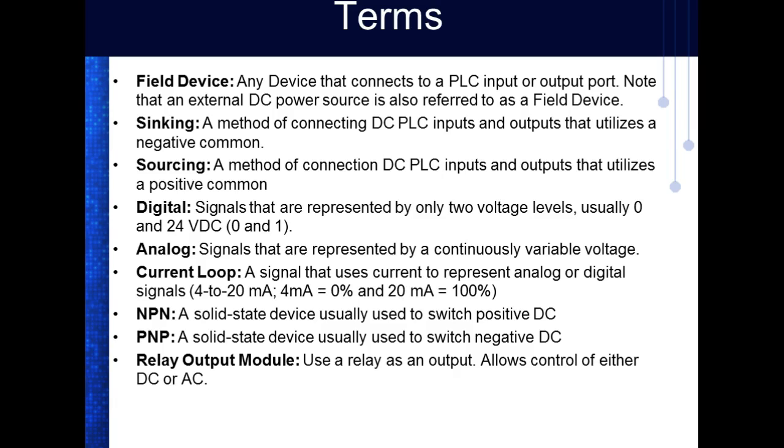And the problem we have is that when we put current through a conductor, it generates a magnetic field. Well, you don't see that little ammeter over there? All I'm doing is swinging a conductor through a magnetic field. That's all I'm doing. Anytime I put current through a conductor, it generates a magnetic field. And if I've got another conductor by that, it does what? It'll induce a voltage in there. Well, when we're dealing with things that are switching, then the magnetic fields are going to change, right?